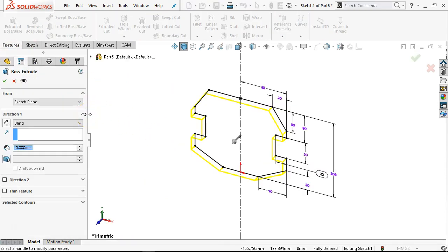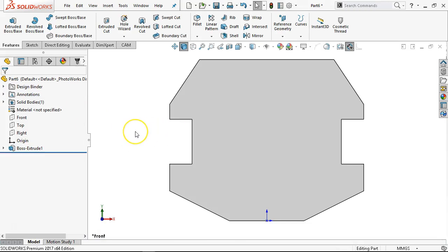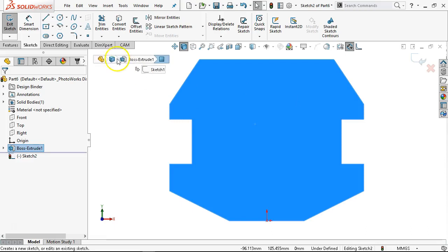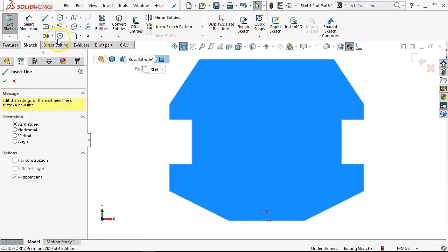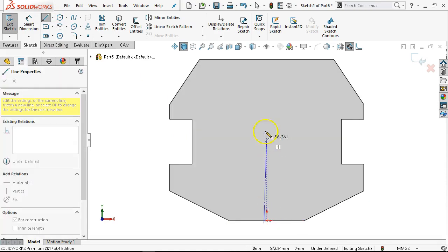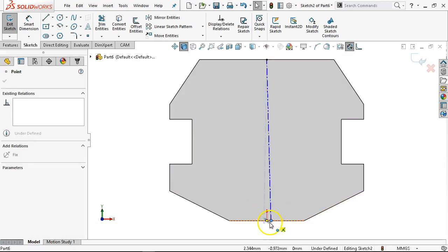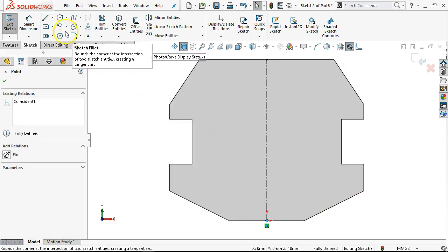So basically I'm looking at this going, this sketch is complicated enough that I don't really want to deal with the spline on top of all those dimensions that I just put in. So the spline then, we'll just go, nope, I didn't want midpoint, I wanted center line, and I still missed. All right, from midpoint, and I'll just grab that endpoint and drag it back to the origin.